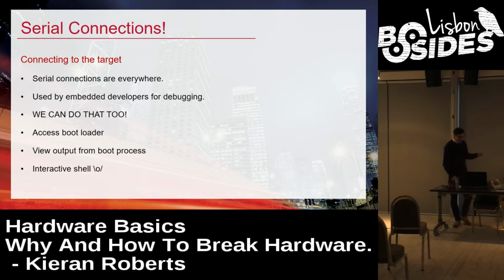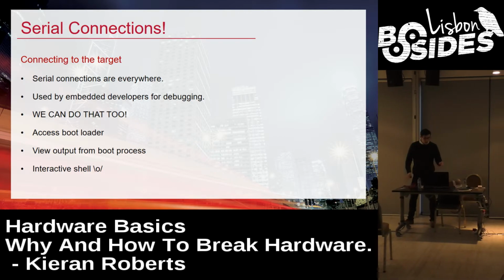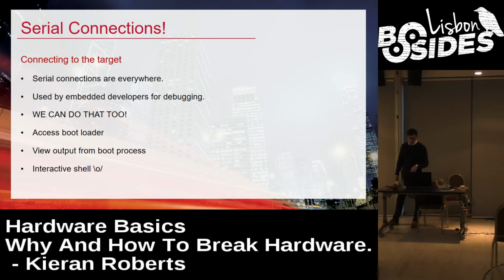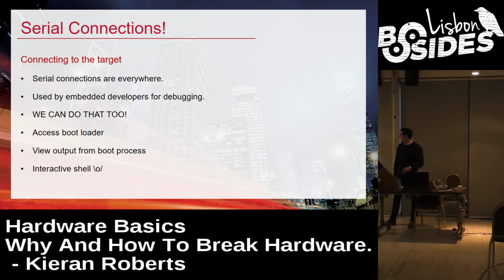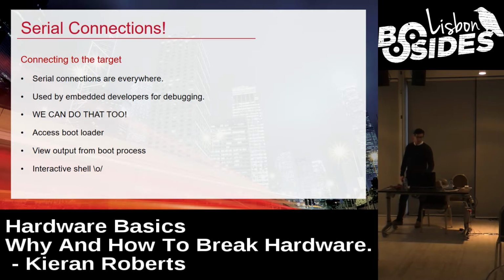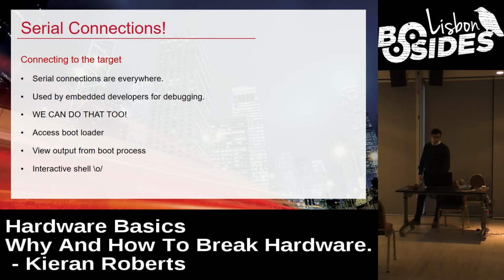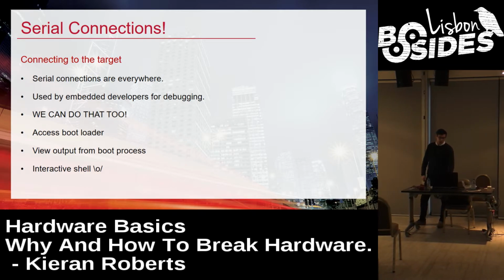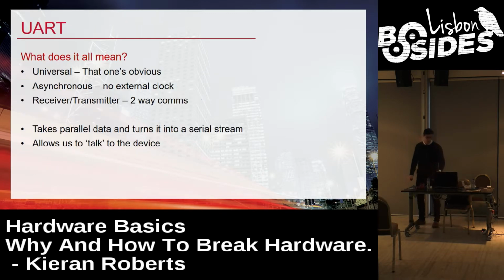Serial connections are on all sorts of things, they're everywhere. They're used by embedded developers to debug their boards when they're being made, and so we can do exactly the same thing. They can provide you access to a bootloader, and allow you to view the boot process as it happens, which can give you some clues later on, and hopefully at the end of it give you an interactive shell. So we're going to specifically talk about the UART.